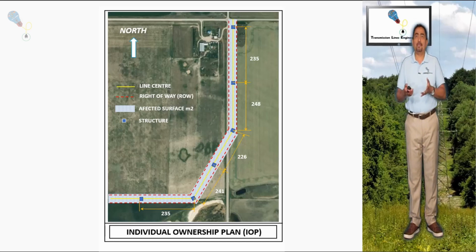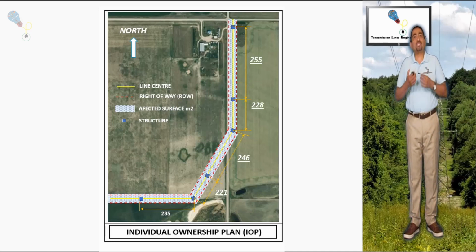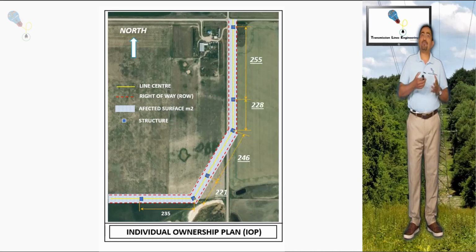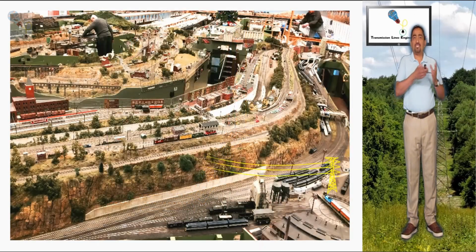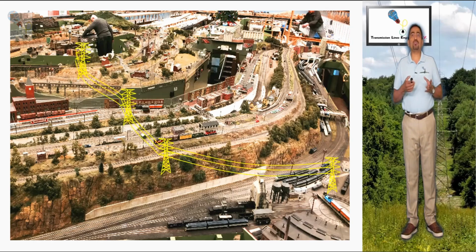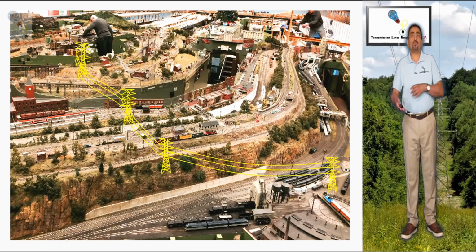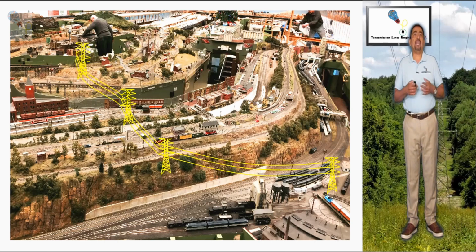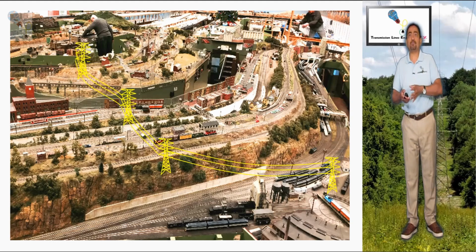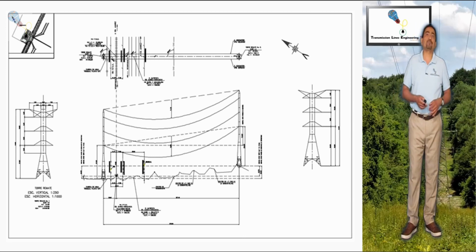As a step number 7, the contractor will update the affected drawings to ownership properties, or the IOPs, to re-evaluate along with the owner and obtain the final authorization for the affected area. This includes not only residential or industrial owners, but also other infrastructure agencies such as railways, crossings with roads, pipelines, rivers, etc. So, to perform the detailed drawings and the calculations to obtain these permits, crossing drawings will be performed and will be seen in a different video.